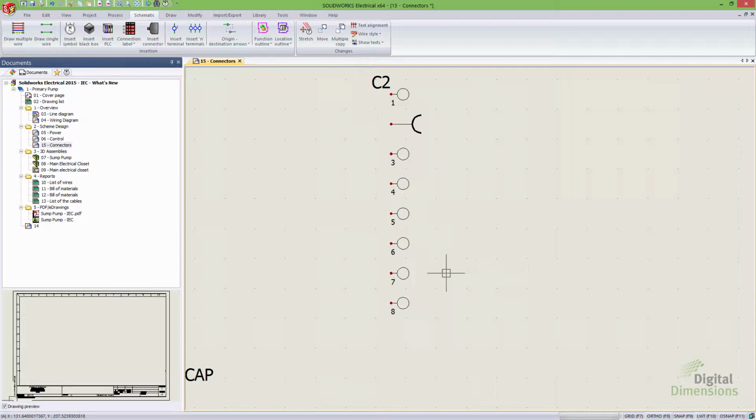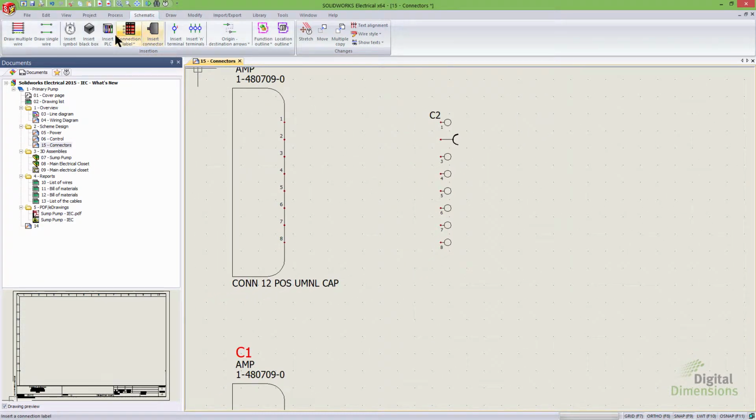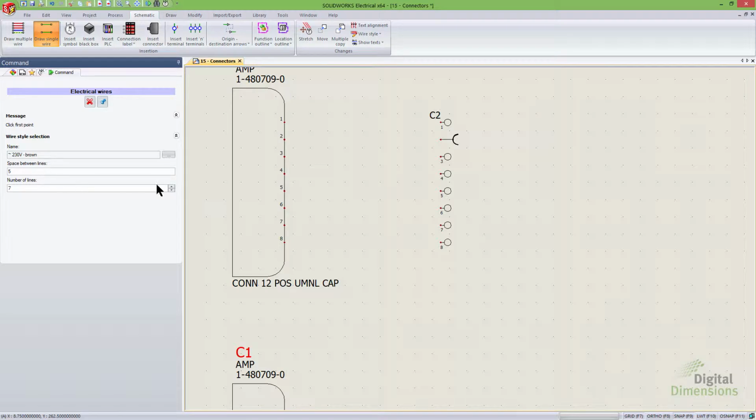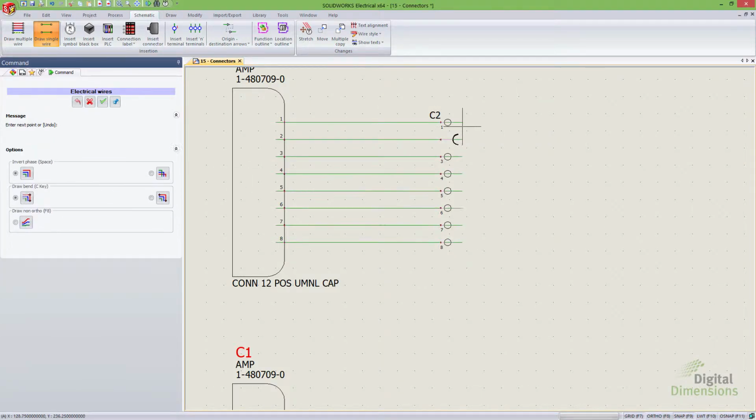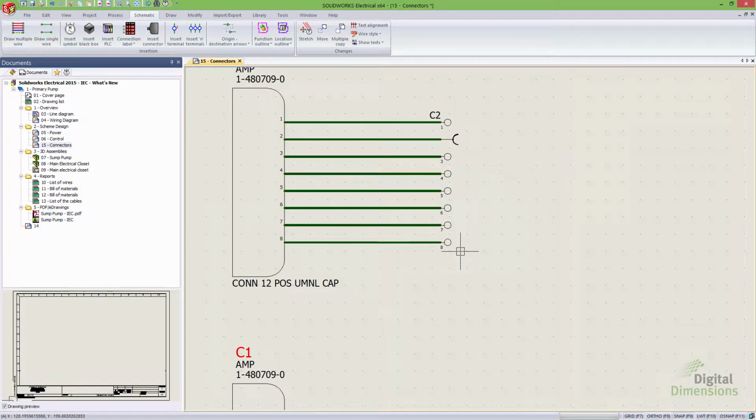So now I've got a majority of my pins one way, and then I've got the one that I need to replace swapped out. So from here, I'll go and add some lines in. So let's just do single line, spacing 5 because I'm in millimeters on this particular one. And then once again I'll just draw across, right click again, and then I've got my wires in there. I think I've got my wires set to a really thick size right now, so I'll need to change that.